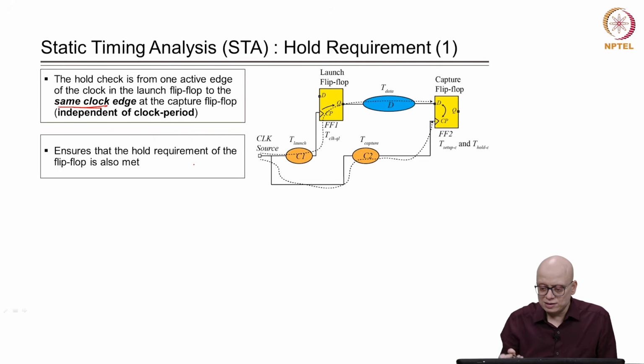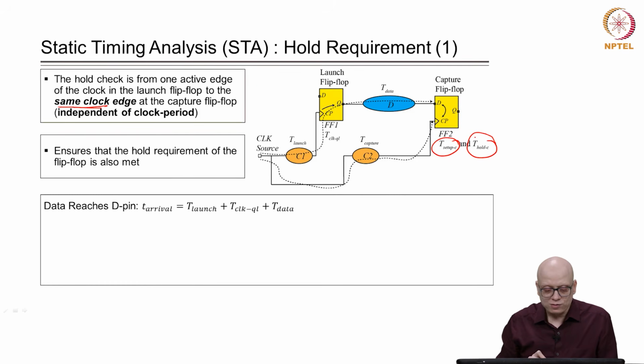So, the circuit is the same, only thing is that instead of the setup time at the capture flip flop, we now consider the hold time. Now, what will be the arrival time of the signal at this point? It will be the same, right.